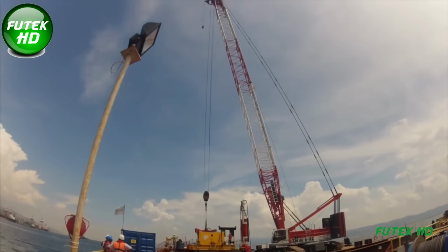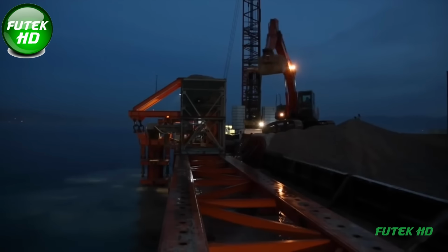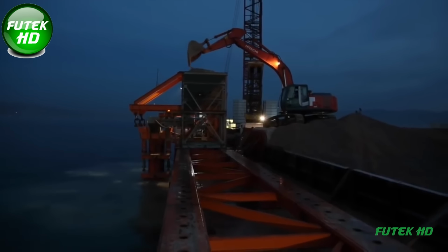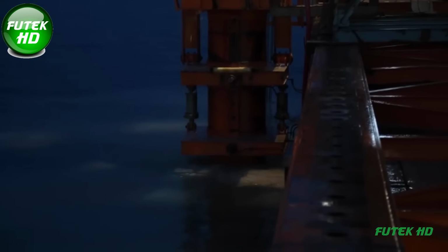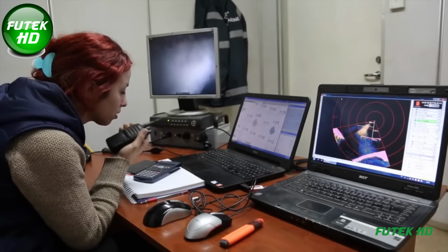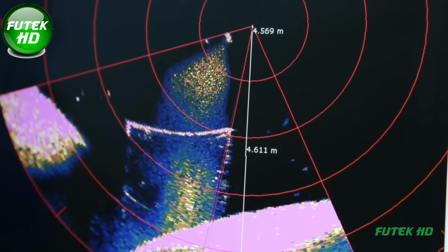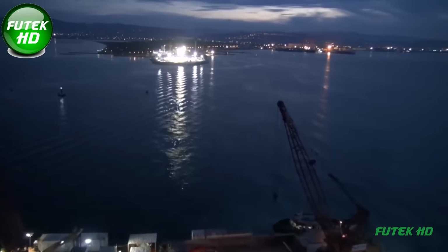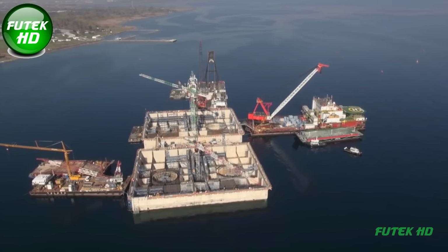Main tower foundations. Innovation meets stability. The main tower foundation construction required not only stability but also seismic resilience. To achieve these goals, the construction utilized a combination of concrete caissons and steel concrete composite shafts. Concrete caissons, pre-constructed on land, were subsequently transported and filled with seawater to sink to their designated depths. Upon reaching the intended level, the caissons were installed on a prepared bed of crushed rock on the seafloor.